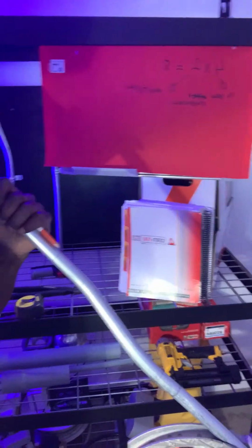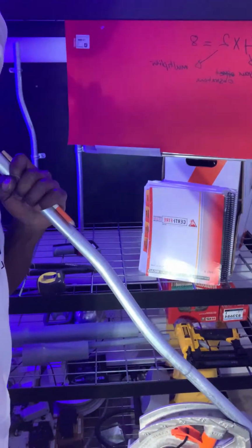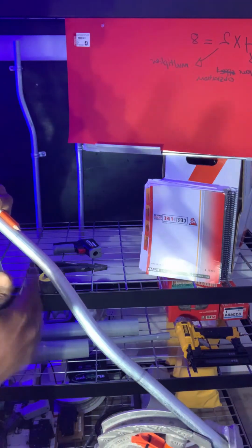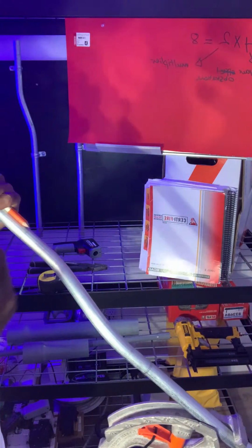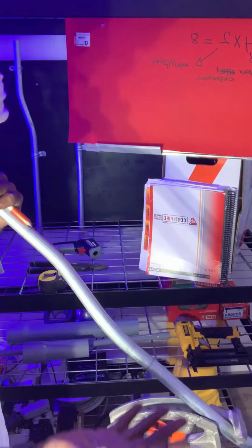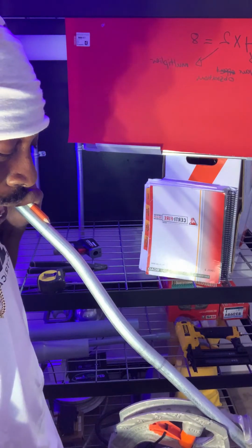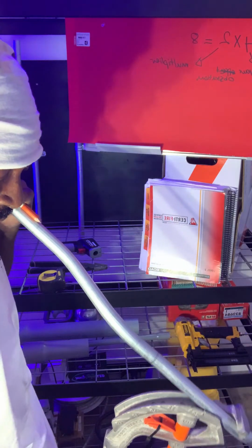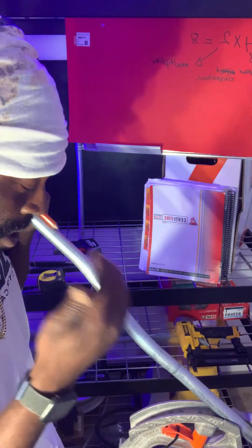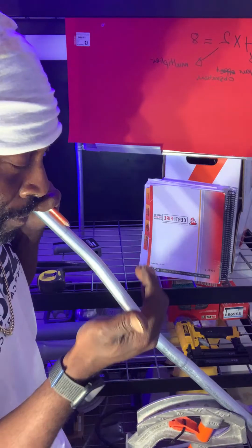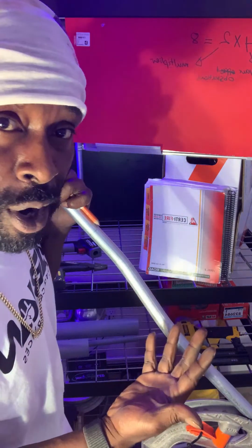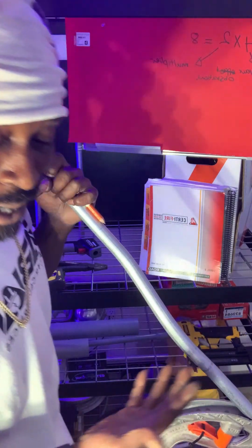Again, you can't go around with the theory, with the practice in the field. Again, how we go about doing that, I take my leg, I wrap it around the actual bender. I have my knee placed on the actual bender itself, and the bender is locked in place. And now I can perform my bend without worrying about dog legs.